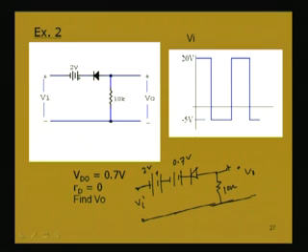Now, what will be this voltage? The voltage across these 2 points is the voltage across this resistance. So, current multiplied by this resistance is the voltage. Now, in the positive half cycle when 20 volt is applied, it is applied in this way. When will it be conducting? You just have to see across these 2 points what will be the potential.